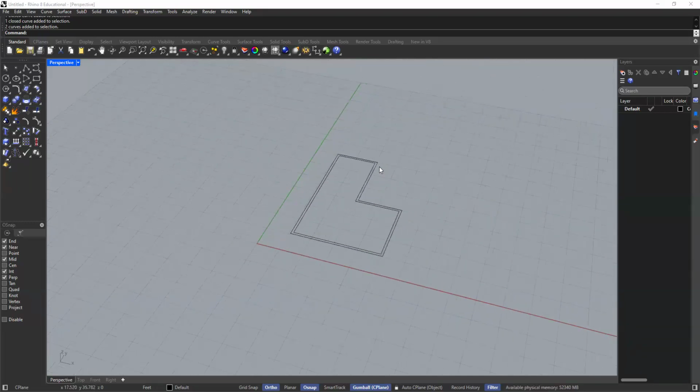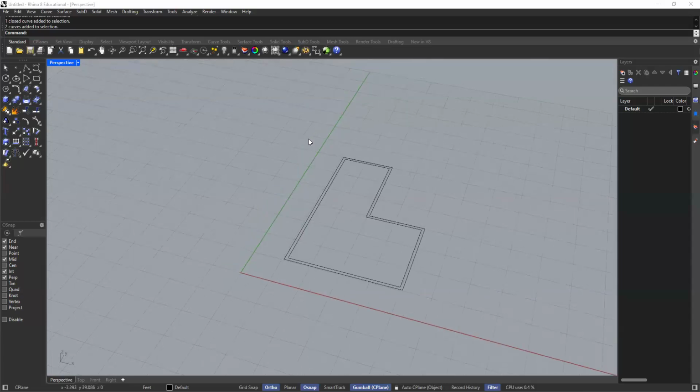Now, really quickly, I want to point out that we have 2 cross windows. A cross window is when I left click, hold down, and drag. There's actually 2 cross windows. If you pay attention, when I click and drag to the left, I get a square with dashed lines, which is different than when I click and go to the right, which is a rectangle with a solid line.